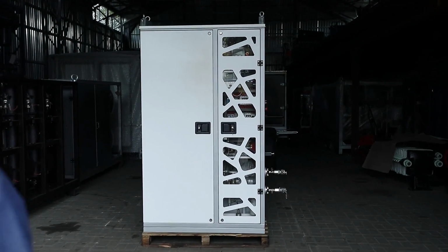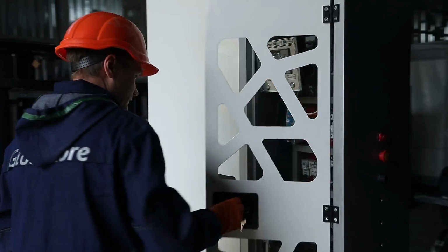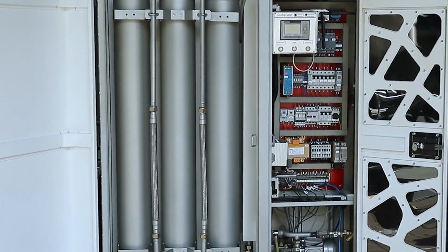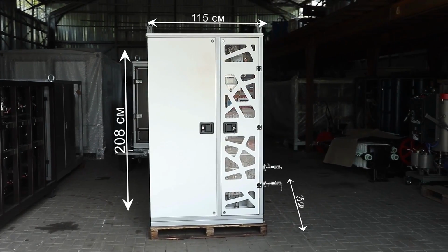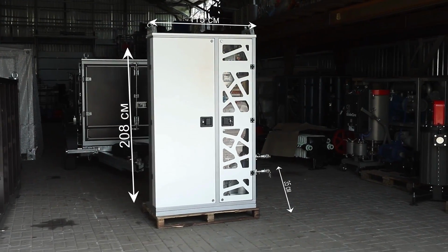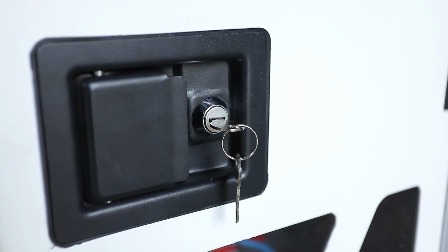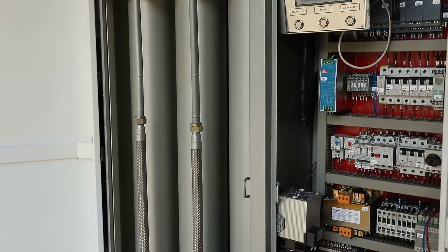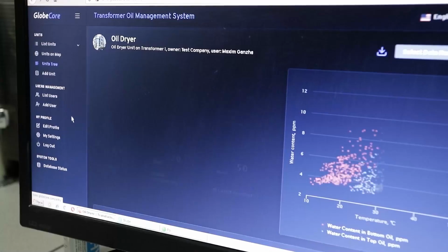Now about the advantages of the TOR system. It has a modern design and consists of the minimum required number of components: sensors, controllers, sorbent cartridges, pumps, and valves. All components are housed in a sealed case 115 centimeters wide, 208 centimeters high, and 35 centimeters long. The housing rating is IP54. The sensors are reliably protected from damage and atmospheric precipitation, so the service life of the system is comparable to the service life of the transformer.